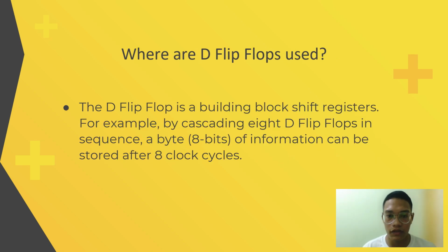Where are D flip-flops used? The D flip-flop is a building block of shift registers. For example, by cascading 8 D flip-flops in sequence, a byte, 8 bits of information, can be stored after 8 clock cycles.